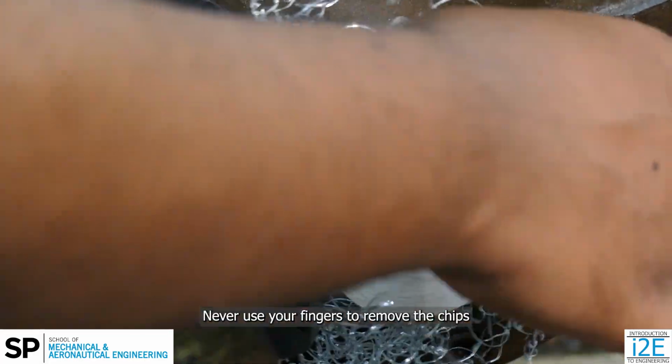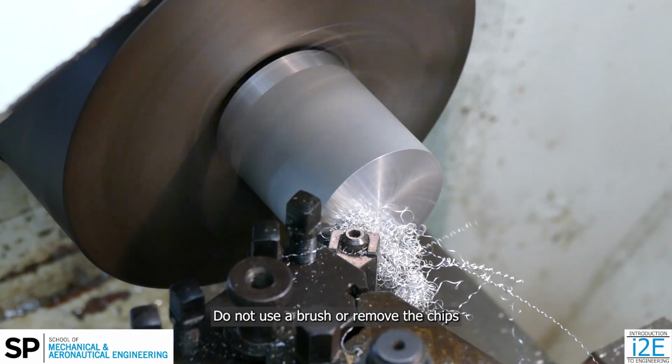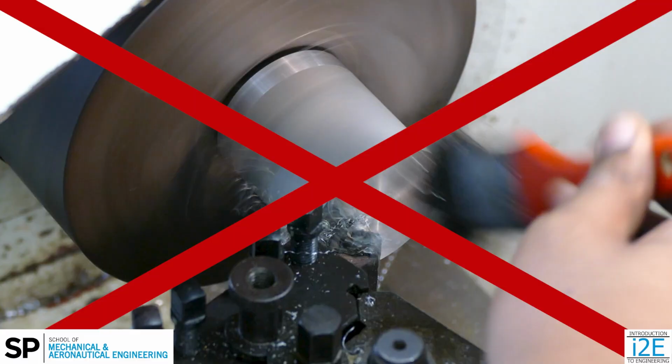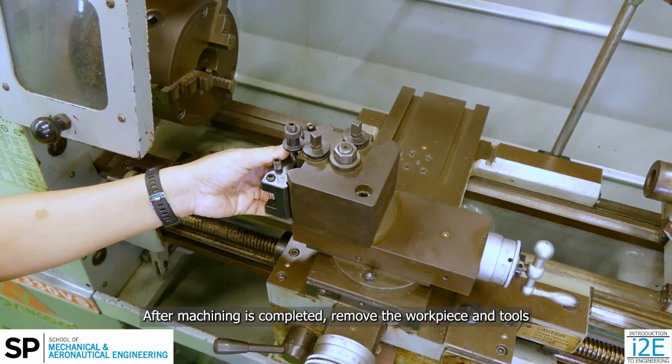Never use your fingers to remove the chips, as they are sharp and hot. Do not use a brush or remove the chips while the workpiece is rotating, as this is dangerous due to entanglement hazards. After machining is completed, remove the workpiece and tools.